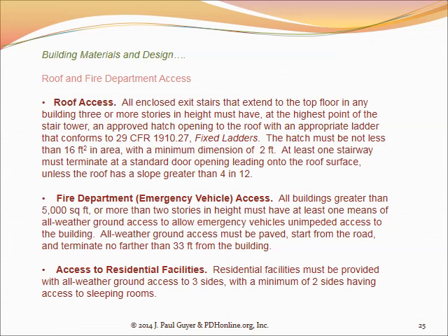So the way this is accommodated in a building is by providing a fire-resistive route for the firefighters to get to where the fire might be. Now, the easiest example to visualize is a high-rise building, and the channel for the firefighters to move to where the fire is and up to the roof is the stairwells.